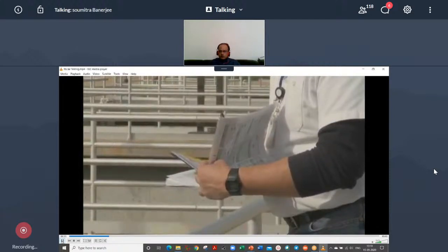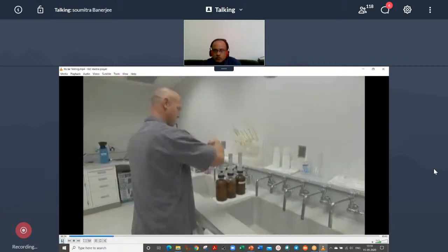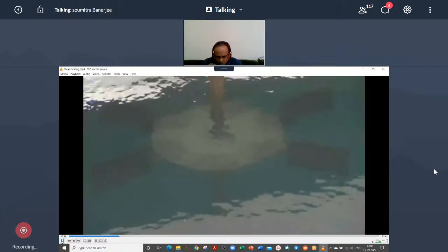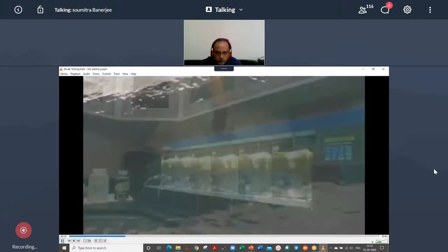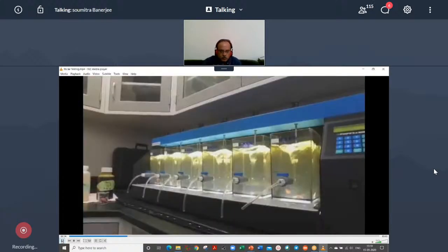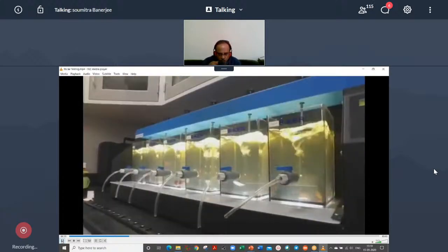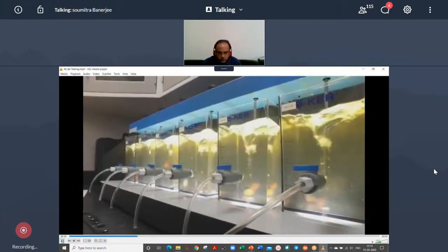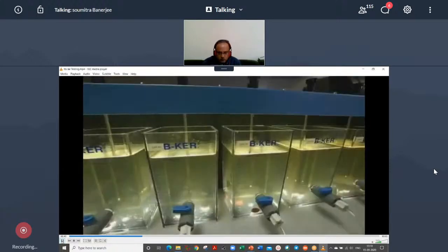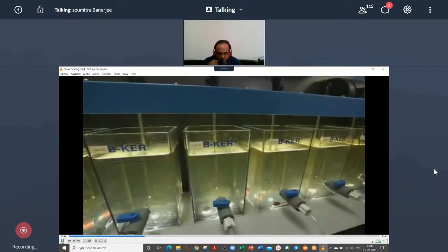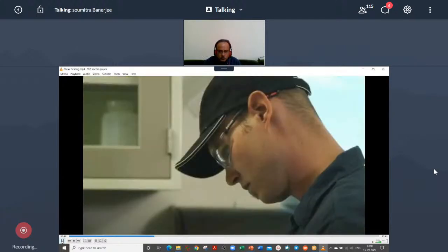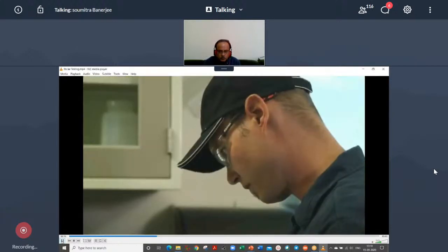To mimic the effect of any changes or adjustments on the water supply, operators use jar tests. It allows them to see what the results will be in the laboratory and predict what will happen full scale without affecting the operation of the plant. Jar testing is an invaluable tool, but can be difficult to perform correctly. When accurate results are generated and correctly applied, jar testing can translate into better treatment and more optimized chemical dosing.